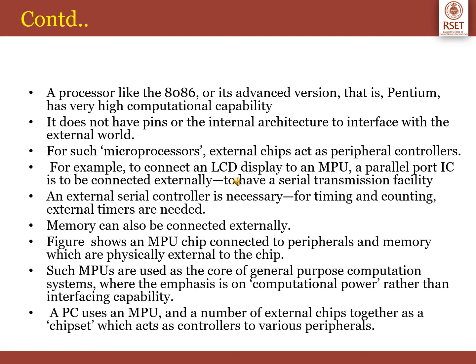It does not have pins or the internal architecture to interface with the external world. For such microprocessors, external chips act as the peripheral controllers. For example, to connect an LCD display to an MPU, a parallel port IC is to be connected externally. To have a serial transmission facility, an external serial controller is necessary. For timing and counting, external timers are needed. Memory can also be connected externally. The figure shows an MPU chip connected to the peripherals and memory which are physically external to the chip.